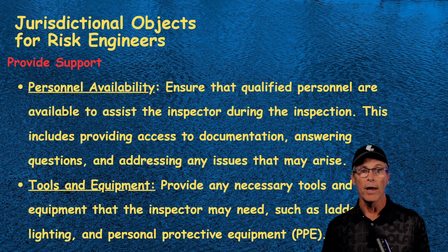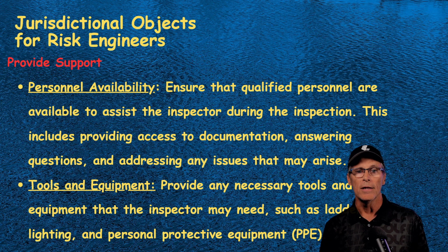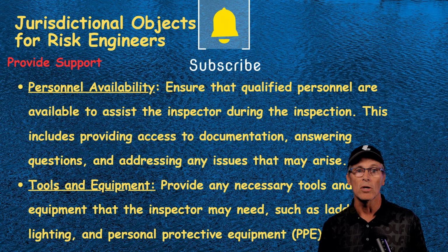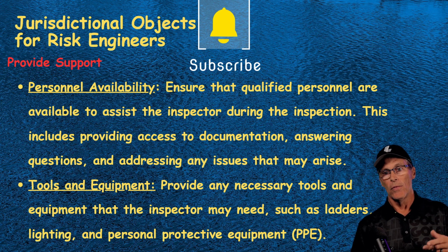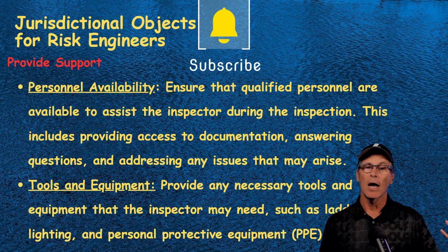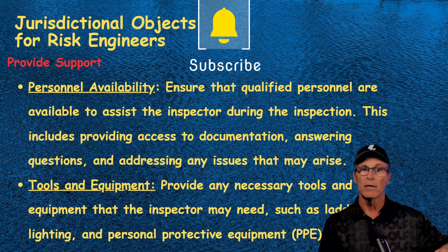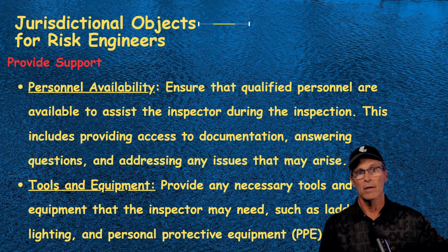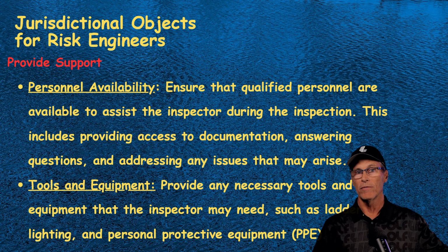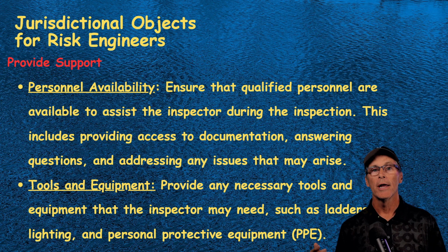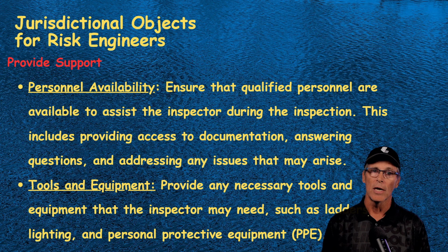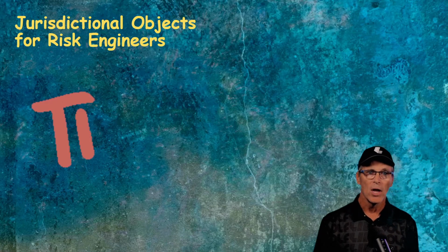I hate to say it, a facility that I was affiliated with did have a jurisdictional object explode after I left that company. And the reason was that when the inspector came, the boiler was operating and it was not possible for the inspector to go down into this dead leg airspace. And since he didn't inspect that area, we have no idea. But that's where the explosion occurred. And it's just another example of make everything available so that they can do the inspections.